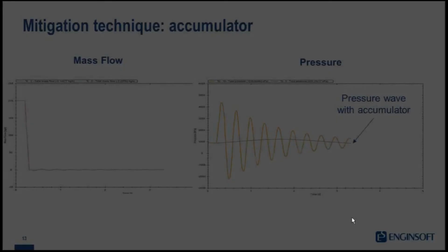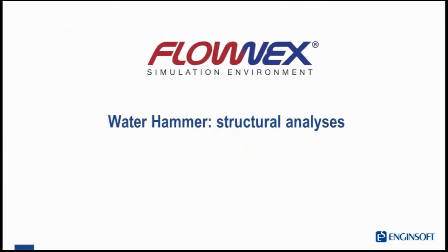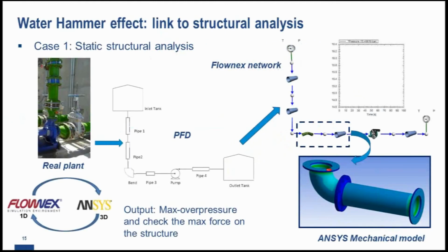So you are able also to link this water hammer effect to structural analysis, which is really important because you have to prevent the water hammer effect, but you have also to be sure that this overpressure is sustainable with the structure of the pipeline.